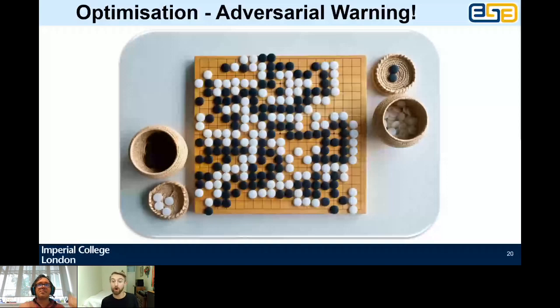But if you tell your optimizer to use the results of a simulation to optimize the microstructure, but you've said that electrons don't matter, then it will, of course, remove all of the CBD, because it probably doesn't have gravity in your simulation, so the particles will stay where they are. And it also doesn't need the CBD to get the electrons where they need to be if you have told it that they aren't a problem. So always your optimization will only optimize the actual model you've given it and not the reality that you were expecting underneath. So be wary of this.